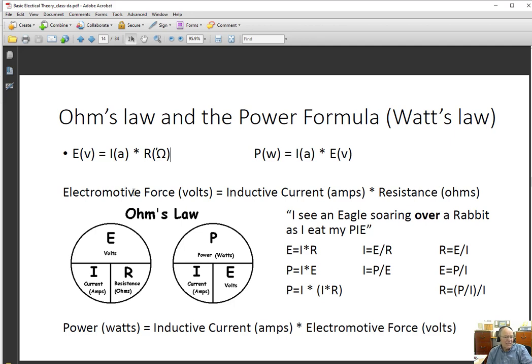So that's Ohm's law, simply applied, and it's really, really useful, especially when combined with the power formula, for you to make some decisions about why can't I plug my toaster oven, my toaster, and my dishwasher in the same circuit at my house without blowing a fuse. It's because of the combination of Ohm's law and the power formula. And it's actually very easy for you to make a decision about how many appliances you can put on one circuit if you understand these formulas. And the math of them could not be easier.